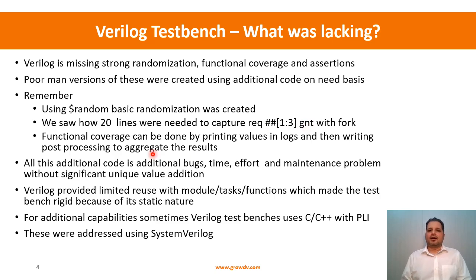It's possible, and we can do functional coverage as well. Like we can print various values that we are simulating. For a counter example, we could print what count we are starting with in the log files, and then write some post-processing scripts in Python or Perl to extract that information and collate it across the tests that we have run, and tell us whether those values that we are interested in have taken place in the test bench.